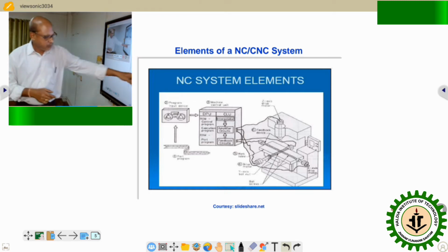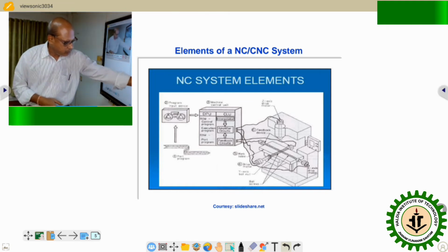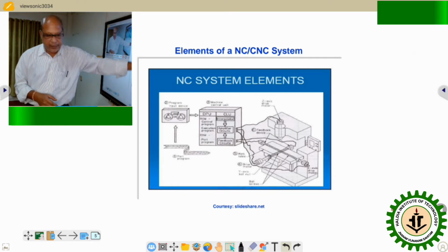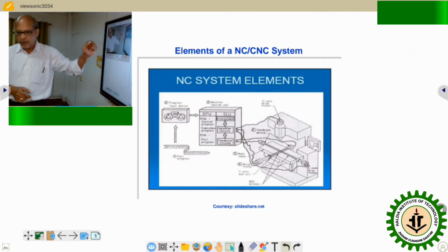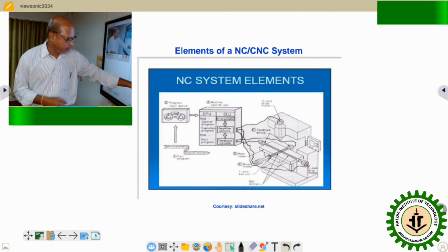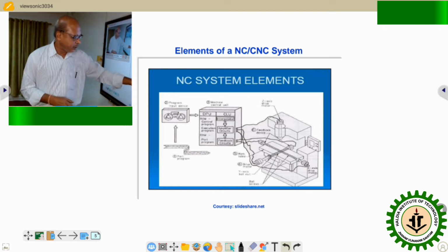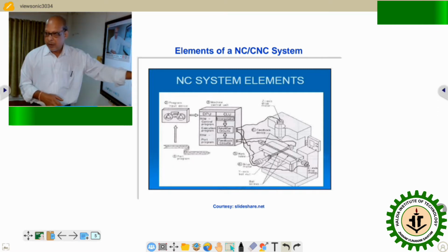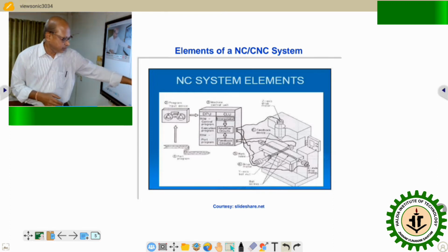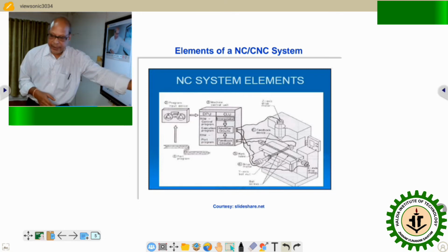Okay, so it is basically an exploded view of a milling machine. There are tables: this is along the x axis, this is along the y axis, and this is along the z axis. It is written x axis drive motor, y axis ball nut, z axis drive motor. This particular drive motor is responsible for imparting motion along the y axis. Only one is shown. So this is the drive motor along the y axis, and this is for the x axis.